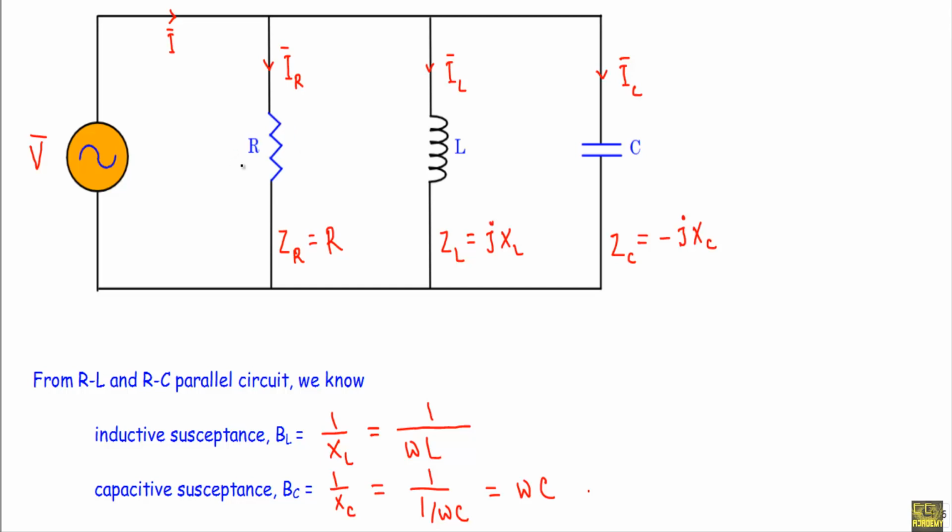See, this is our resistor R, this is inductor L, and this is the capacitor C. One end of this R, L, and C are connected at this point. Another end of R, L, and C are connected at this point. So this is our RLC parallel circuit, which is connected across a sinusoidal voltage source. As this is sinusoidal voltage source, the instantaneous voltage equation will be v(t) equal to Vm sine omega t.